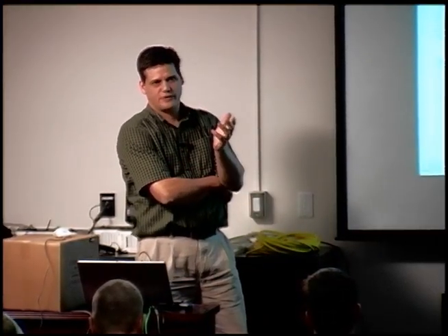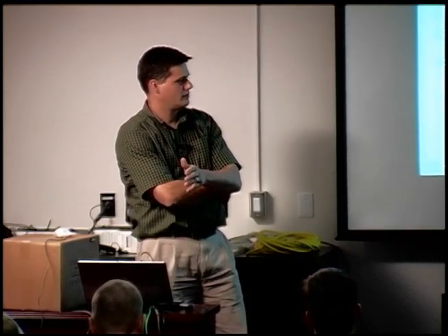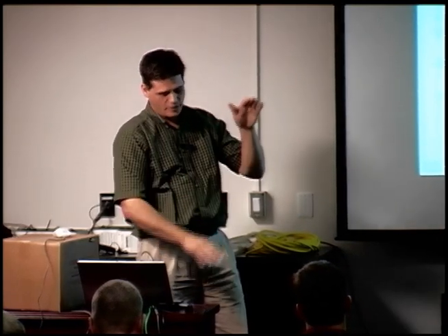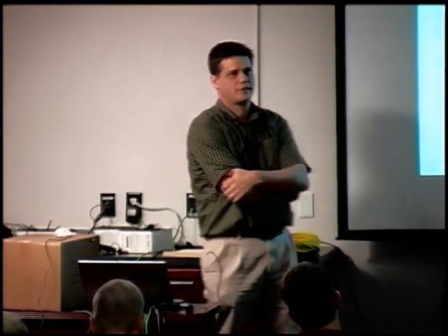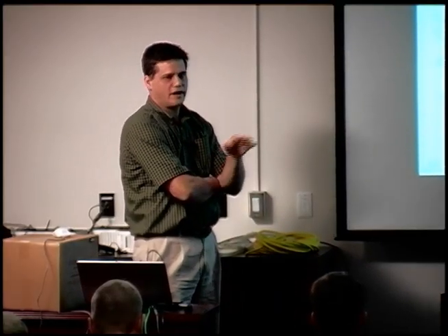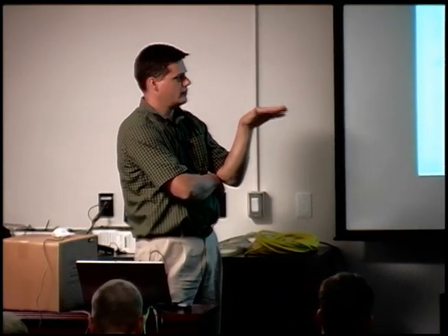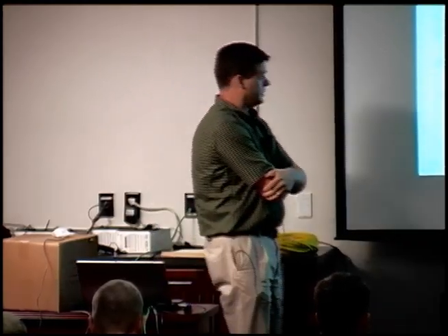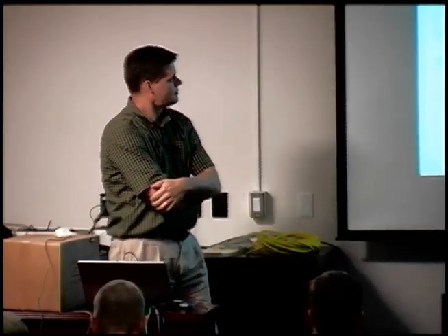So you have to realize you're going to get more driving resistance if you're leaving the soil there and you're going to dig it out later. Now most of the time the soil on the top, as Ken mentioned, is junk, so it's probably not going to matter too much, but in this case we were doing fairly deep encasements, and it was pretty good soil, so it made a pretty big difference in terms of what we should put down for what we used to call theoretical driving resistance, and now we're calling target nominal driving resistance. So just be aware of that.